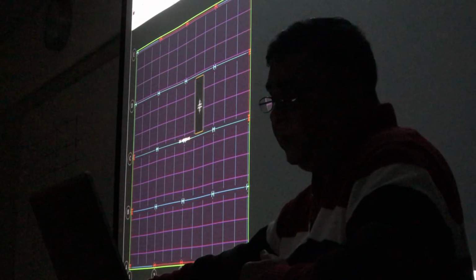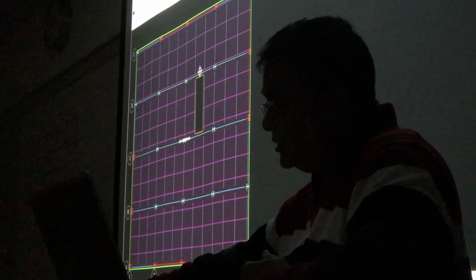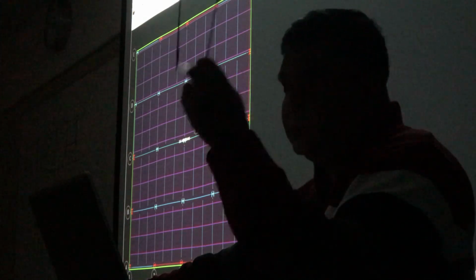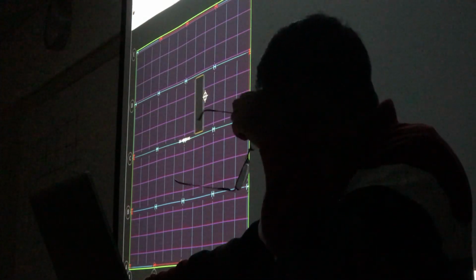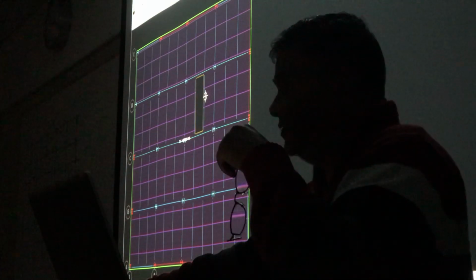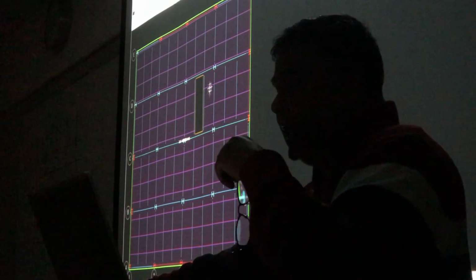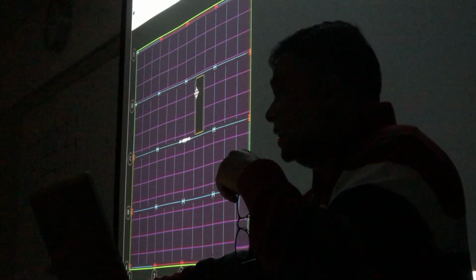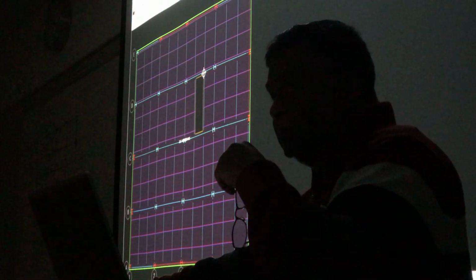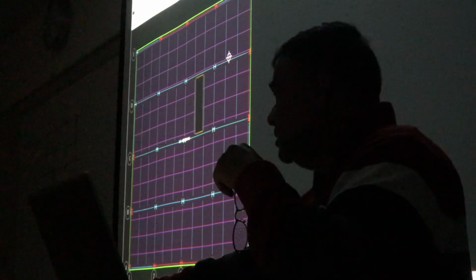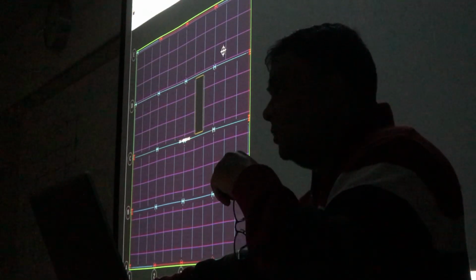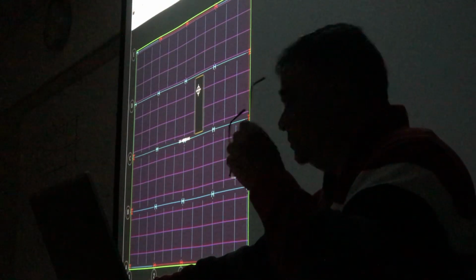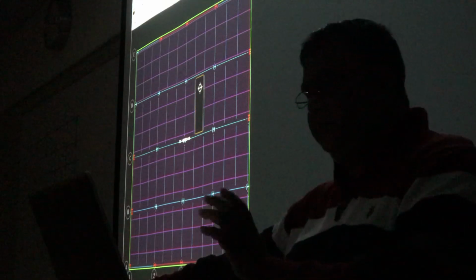Now remember, any opening that you may have in a slab system, doesn't matter whether it's a timber or plywood shear wall, plywood roof or floor, or if it is steel, or if it is concrete, it has to be bounded by beams. That means we need to stitch it. Otherwise, there will be the possibility of crack generation and crack propagation. So always you have to provide a boundary for an opening. Okay, I'm just going to be leaving with that.